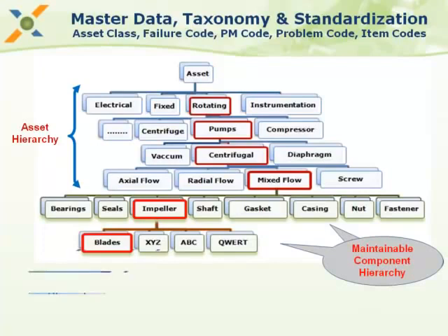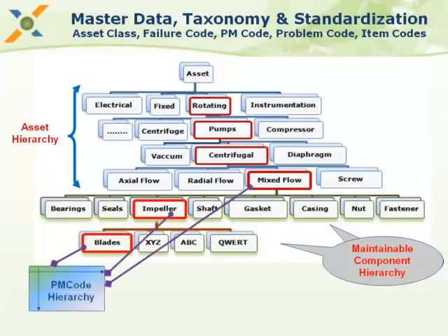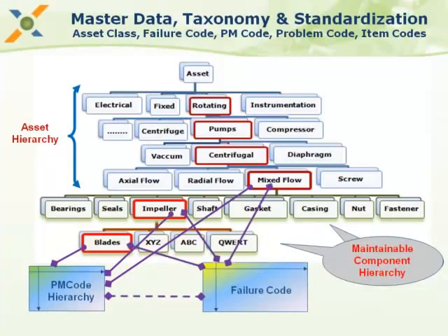Another thing we noticed is on the PM itself, the PM categories. If we have it at an asset hierarchy level, it will also help you in building a relationship between failure and the PM. When you attach an asset to a particular place in this hierarchy, then you know that asset can be monitored in many, many ways. So these are simple things, but they can really help in analyzing data.